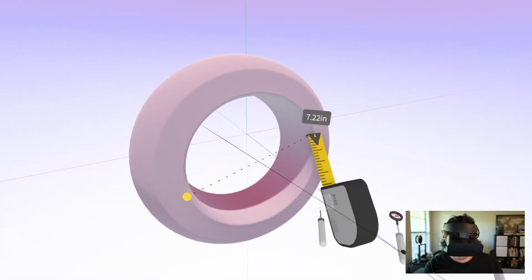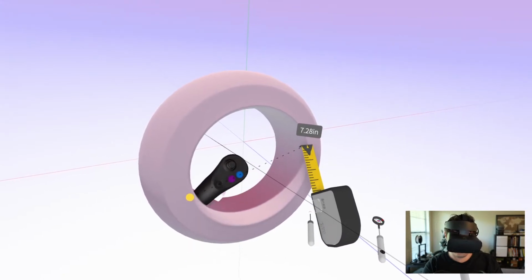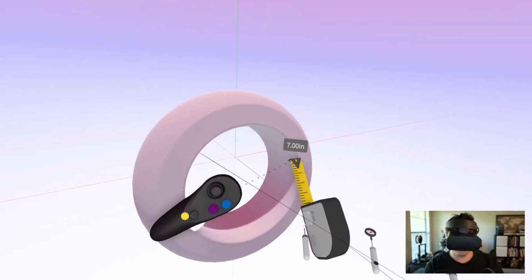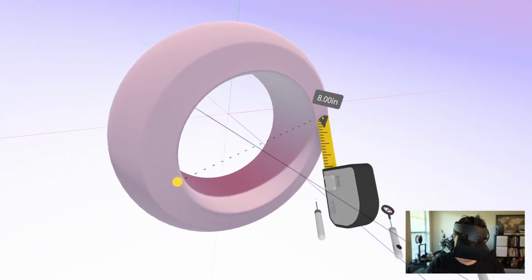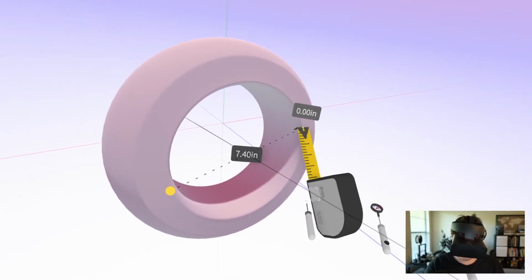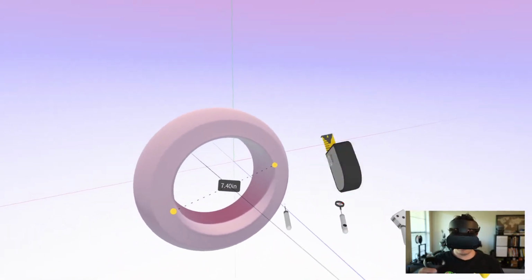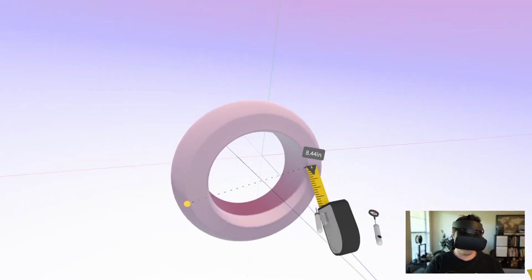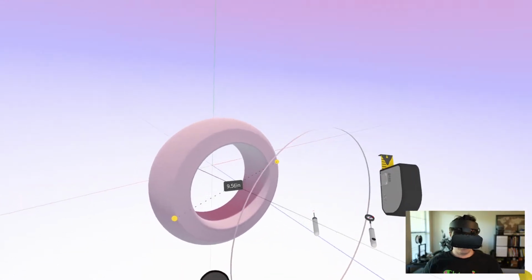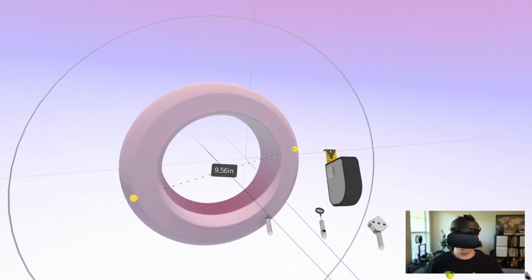But as long as you're crossing through here, you can see the axis that the revolve was drawn on. So as long as you're crossing through that, you're probably getting it directly across. And so we're just gonna tap it there. So it looks like it's about a 7.4 inch diameter. And then we can additionally measure the outer diameter of this crease. So this gives you a general idea of what the diameter is. And so you're able to measure things in Gravity Sketch, which is really helpful.